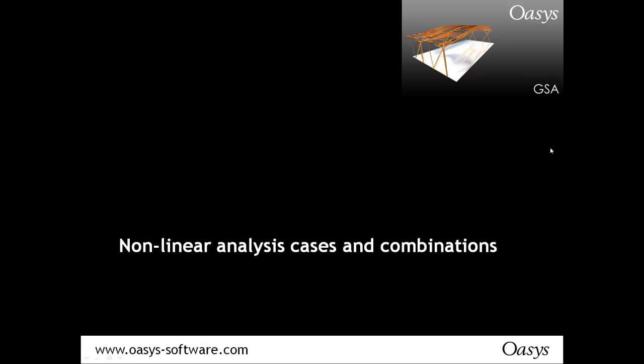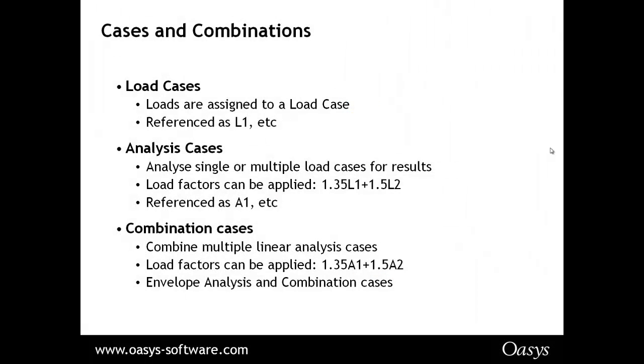So, combinations. If you're not familiar with nonlinear analysis, this can be a confusing area because a lot of it's very familiar but not quite familiar enough. The thing to remember in GSA is that you apply loads in a load case, and when you analyse them they're put into an analysis case.